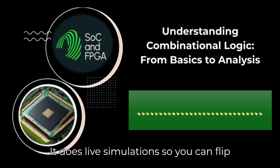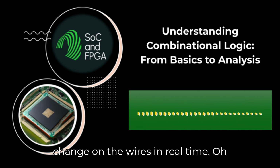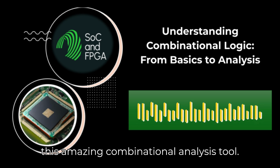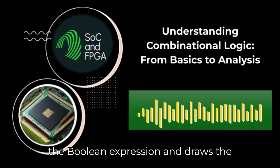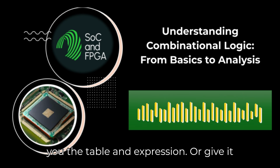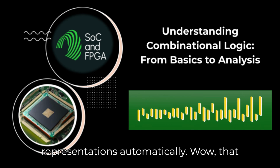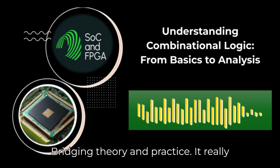It does live simulations, so you can flip input switches and see the zeros and ones change on the wires in real time. Oh, cool. Instant feedback. Yeah, and it supports hierarchical design. Plus, it has this amazing combinational analysis tool. You can give it a truth table, it derives the Boolean expression and draws the circuit. Or give it a circuit, it gives you the table and expression. Or give it the expression. You get the idea. It converts between all 3 representations automatically. Wow, that sounds like a perfect learning tool. Bridging theory and practice? It really is.